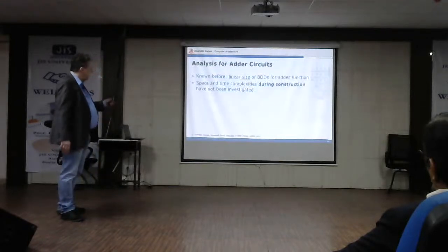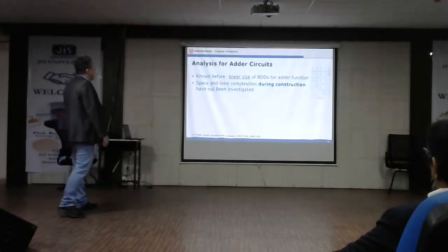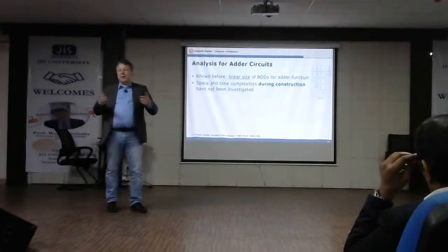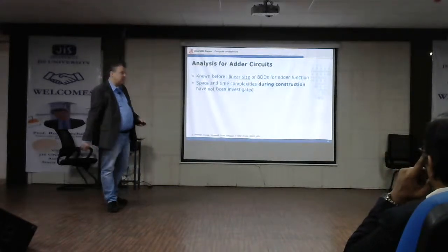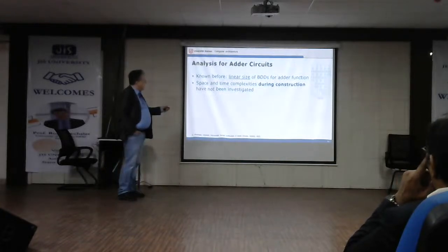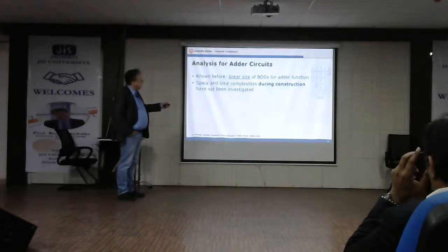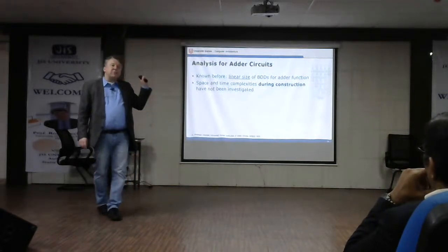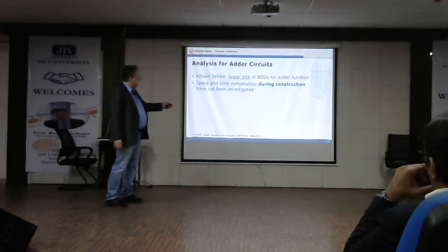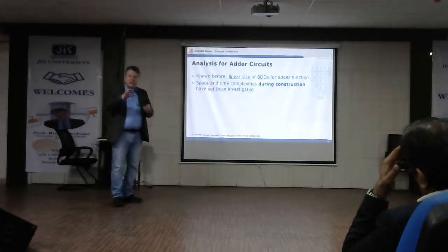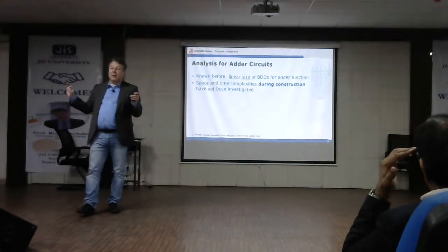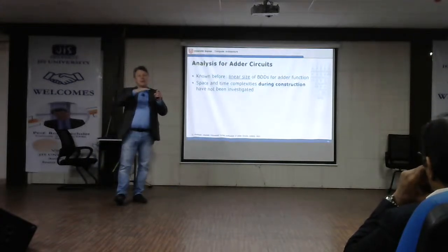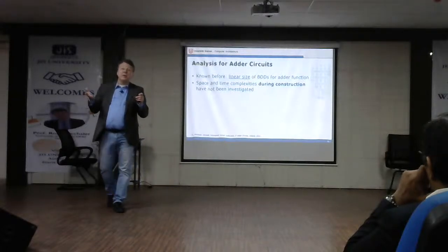And now what we have done, and this started around 3 years back, is that we started with a circuit structure that is very well understood, namely adders. Adders are in some sense non-trivial, but the most simple one you can think of. And it was known for BDDs that they have a linear size for the adder function. That was known before. But for the final representation, now we look in the verification process that also the memory peaks never become larger during the construction. That is the important part, that we really want to see the verification always has an upper bound regarding runtime and memory requirement.